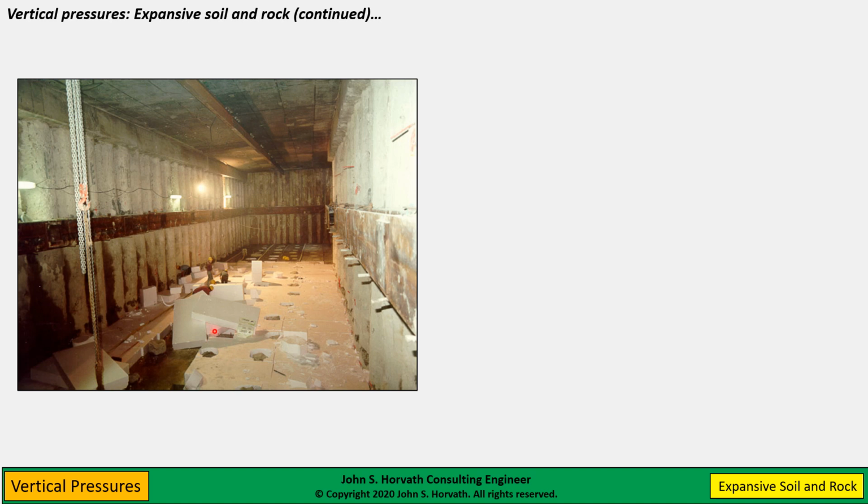That's why it doesn't look purely white. It is artificially colored pink. And as I note in my primer on geofoams, expanded polystyrene is inherently white in color. And that's why if you see the ubiquitous foam coffee cup, it is white in color. EPS is inherently white in color, so is resilient EPS.